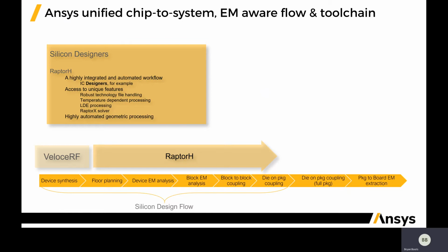It provides some unique features with robust technology file handling and perhaps more importantly, encrypted technology handling, but also consideration for layout dependent effects in advanced processes and access to the peak solver of RaptorX. This flow is very tightly integrated with third-party platforms, and it's really focused on extraction and back annotation into those workflows.